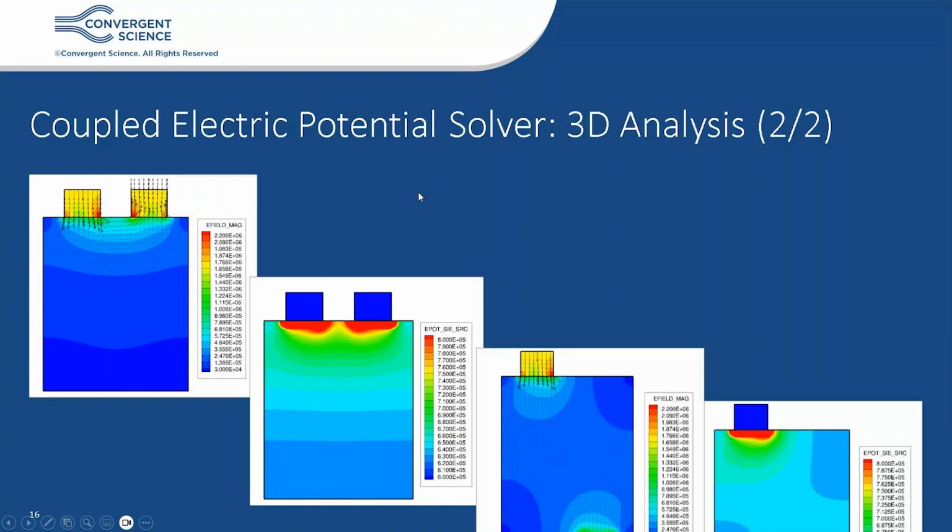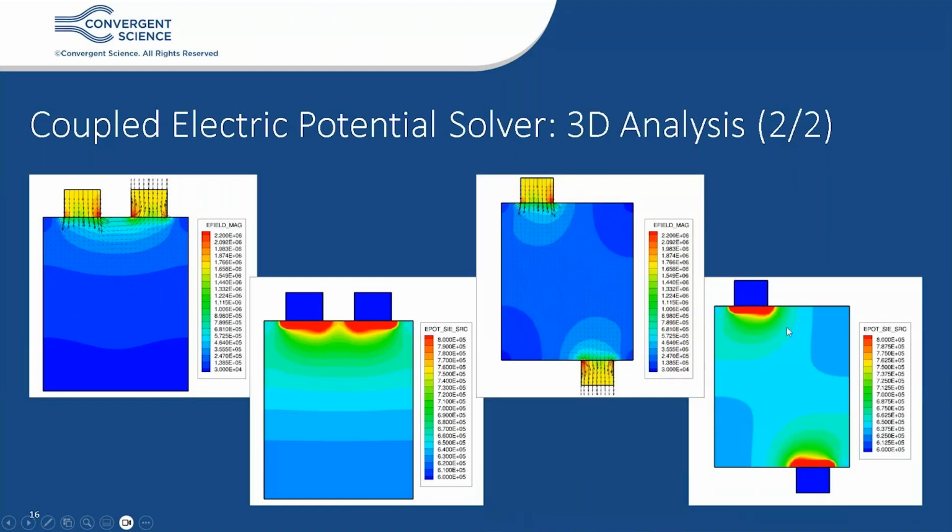So this can allow engineers to investigate better designs for pouch cells. For example, an opposed tab design will ensure that the heat generation is more uniform inside the battery and the temperatures are more uniform and the battery ages uniformly as opposed to non-uniformly in the previous designs.